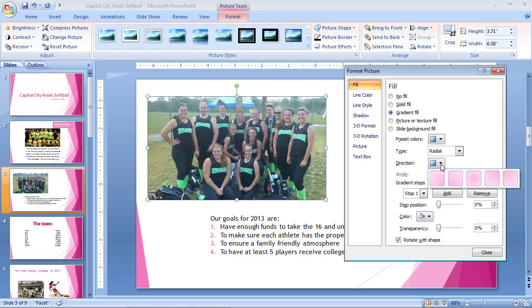If you selected a linear gradient type, then you may select the angle at which the gradient changes by entering the desired angle in degrees into the angle spinner box. You can use the Gradient Stop section to set the number and appearance of changing points in the gradient's color scheme. At its most basic level, a gradient must have at least 2 gradient stops. For example, if a gradient changed from black to white in a linear fashion, then it would have at least 2 gradient stops. You can have more if desired.